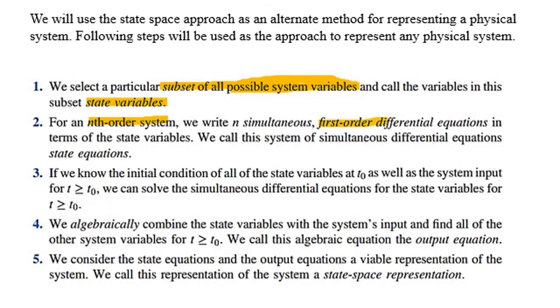In the second step, we will represent these state variables in the form of first order differential or difference equations known as state equations. Let us say we have a system of nth order. For this, n state variables of the system will be represented in n first order simultaneous differential equations.